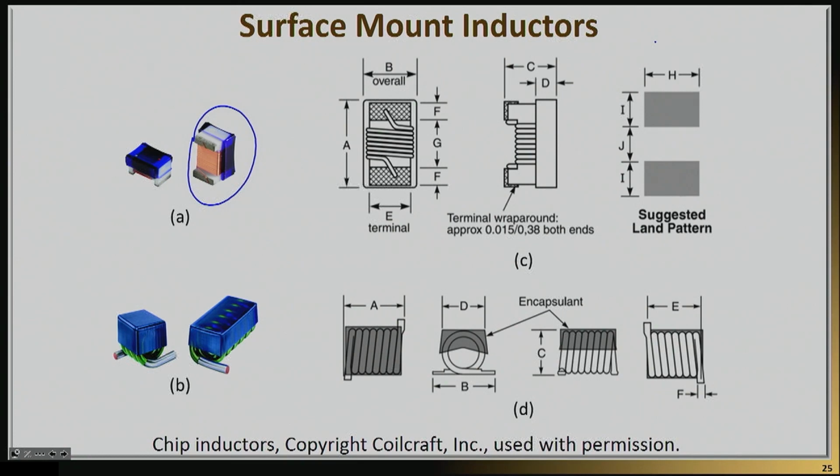The main characteristic of an off-chip component is that it's much larger and therefore much higher quality than the on-chip one. So it's not unusual to get high quality inductors off chip with a Q factor in the order of 100, while the same thing on chip would have cost you a Q of 10. So of course the drawback is that you now have a higher cost.